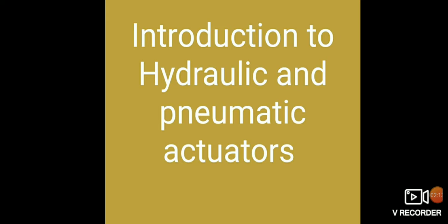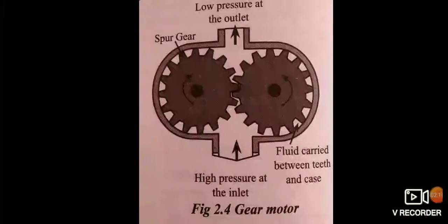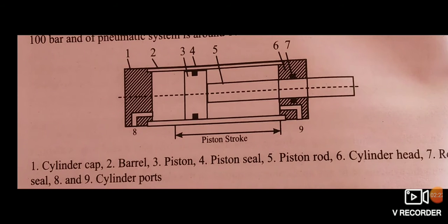Now, the hydraulic cylinders convert the hydraulic power into mechanical power, performing rectilinear motion. Cylinders are linear actuators that can push and pull, and when mounted around a joint, can actuate rotary motion. The pressure of the input oil is converted into the force acting on the piston. The construction of hydraulic actuators is shown in a sketch.